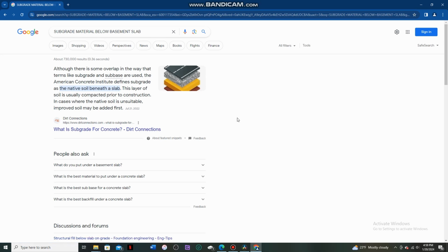It could either be a porous material, like stone, such as crush and run, where there is good airflow through that, or it could be clay. Maybe the person who laid the foundation put it on top of clay instead of using stone, as they should have. Understanding your material underneath will help select your fan, because if you have a very thick clay underneath your slab, your fan is going to have to suck a lot harder. If it's porous, air can easily be sucked through the rocks and taken out of your home.